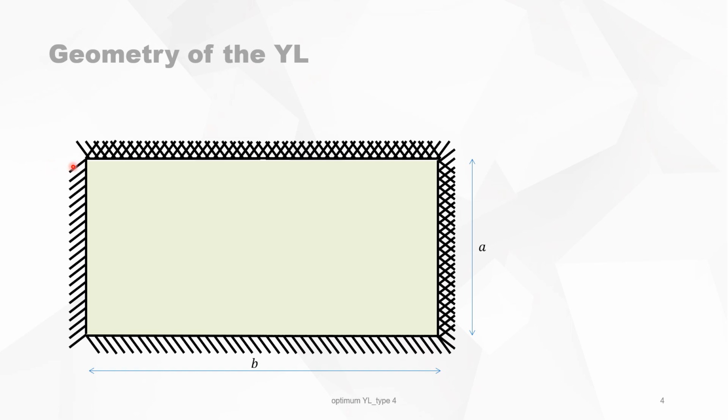Using the yield line method, we know that the axes of rotation are the 4 support lines of the slab. And when the rotation axes come together and cross, the yield line starts in the corner with an angle beta 1.